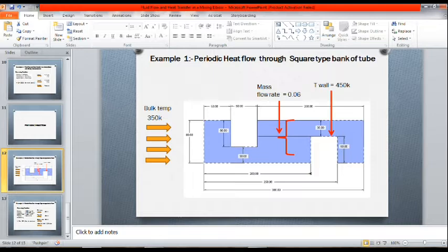The system that is modeled is a bank of tubes containing flowing fluid at one temperature that is immersed in a second fluid in a cross flow at a different temperature. Both fluids are water, and the flow is classified as laminar and steady with a Reynolds number of 100. The mass flow rate of the cross flow is known, and the model is used to predict the flow and temperature field that result from the convective heat transfer.